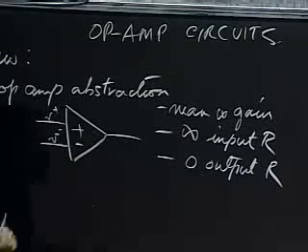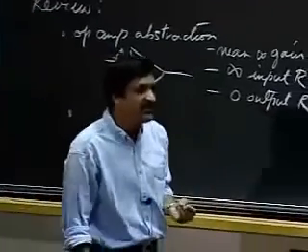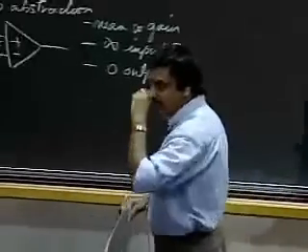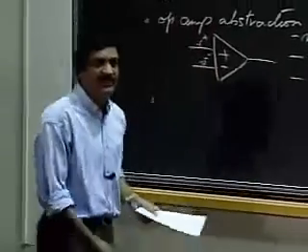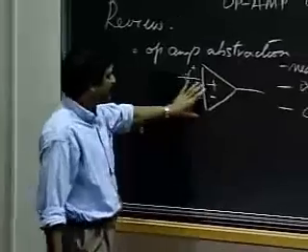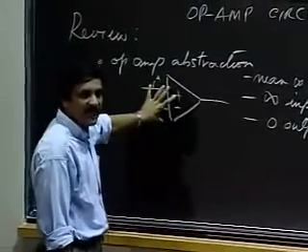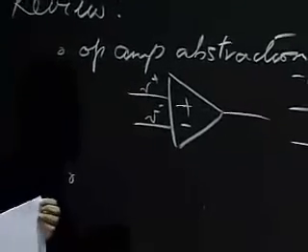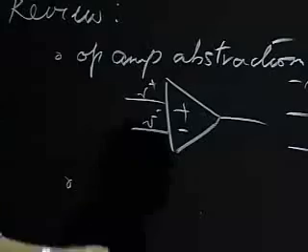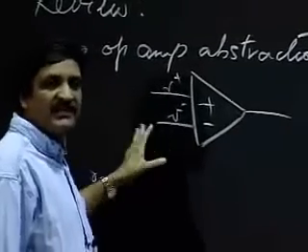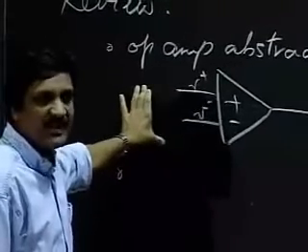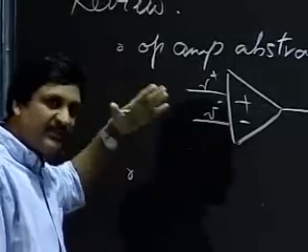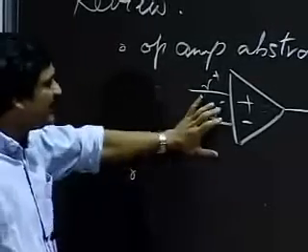So the op-amp is a huge workhorse of the analog industry. You will see, based both on what you've done on Tuesday and Wednesday, but also today, that it's very, very simple to build circuits using the op-amp. Okay, when you use the amplifier, you don't have to worry about things like nonlinear analysis. You don't have to worry about, am I really meeting the criteria for saturation limits and so on.